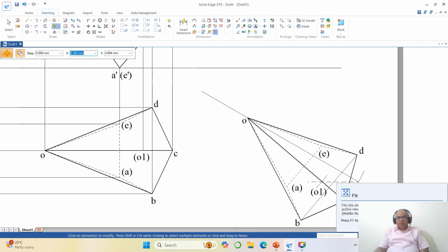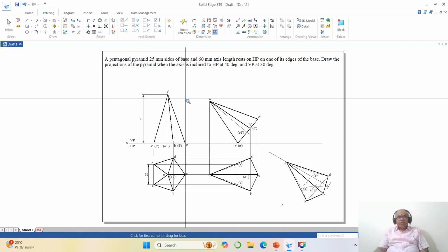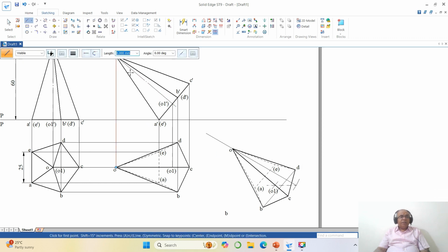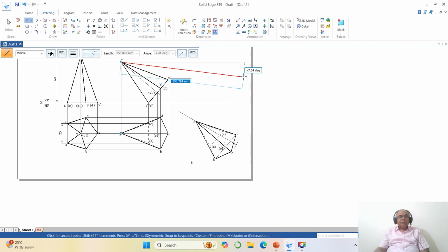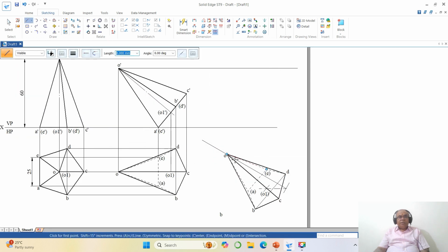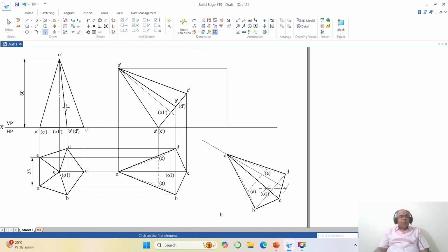Once you do that, now I want to name them. The name is also over, and then draw a horizontal projector from O dash, and then come down to zoom window. Now you go to line command, draw a line from endpoint with the horizontal line, vertical line. Go to trim corner between these two. Once you do that, then go to line, take this endpoint onto this. Similarly, on this endpoint onto this, and go to trim.